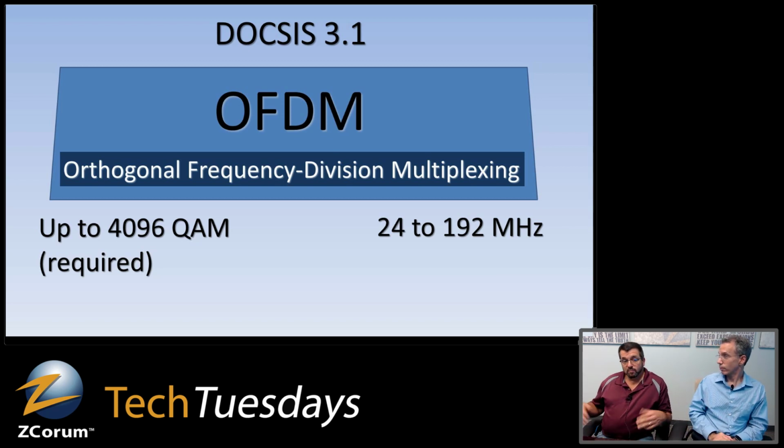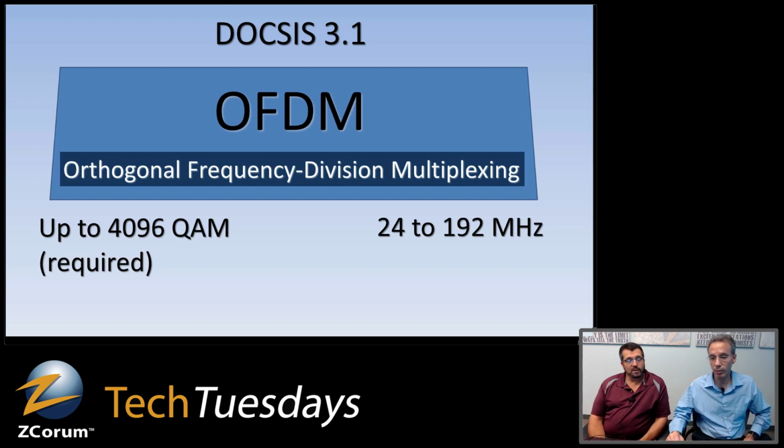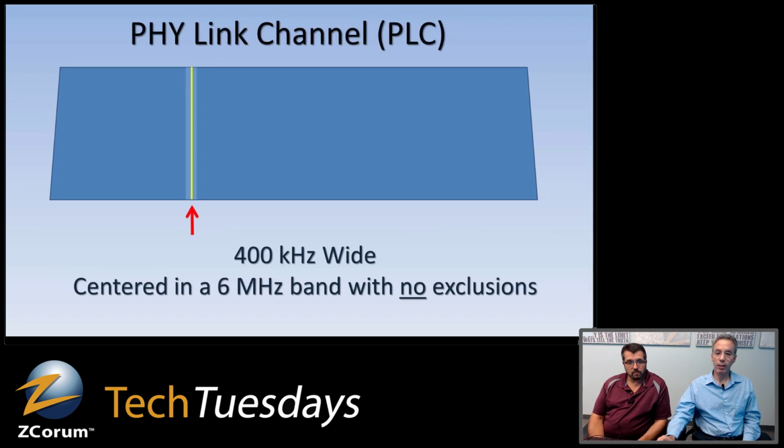And I mean, it is one big channel, but there are thousands of subcarriers in there, depending on your spacing. It could be either roughly 4,000 or 8,000 little sub-slices. It depends on how you set it up. Yeah, and so again, the orthogonal part is different and new, but it's new for cable. The OFDM part has been done with Wi-Fi, wireless, and even DSL. Yeah, it's been around for a while, definitely in cellular. You're seeing it in Wi-Fi too. Yeah, so it's new for cable. Satellite.